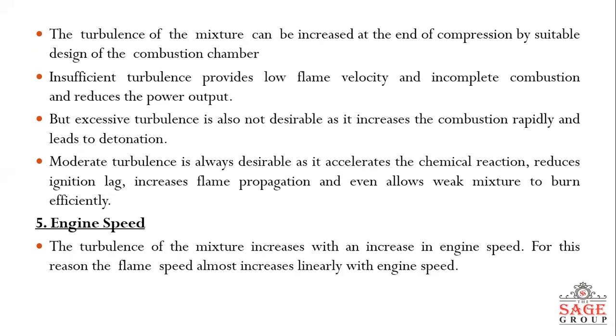The flame speed is quite low in case of non-turbulent mixture and increases with increase in turbulence. It is mainly due to additional physical intermixing of the burning and unburnt particles at the flame front, which expedites reaction by increasing the rate of contact.